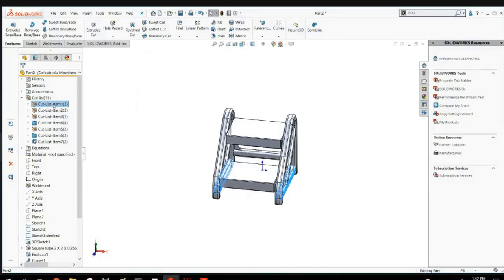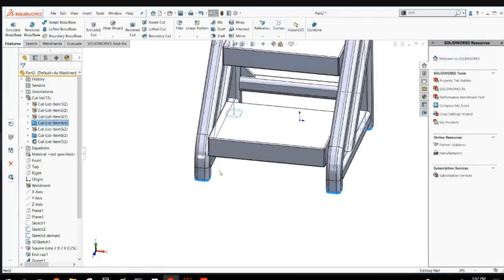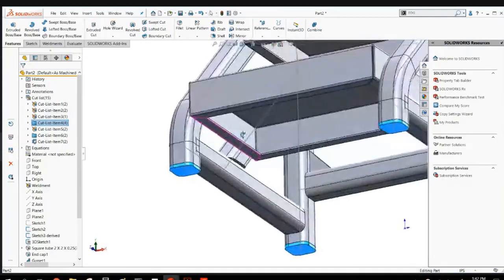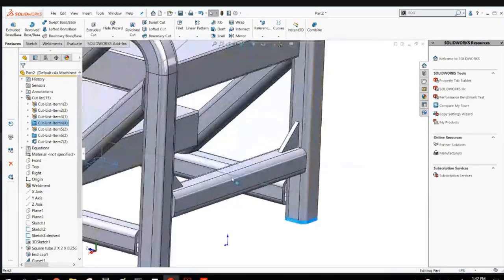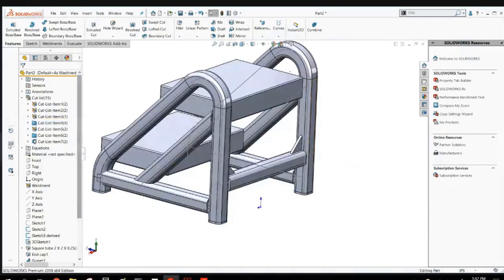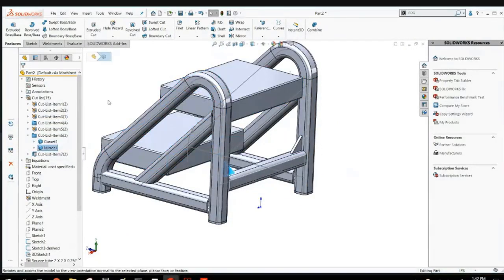It's using a weldment structural member. When you've got a folder like this, that's something that's been extruded, where it doesn't have a cross-sectional shape. It's not an I-beam or a piece of pipe or anything like that. So those gussets and the end caps have been grouped with those folders.